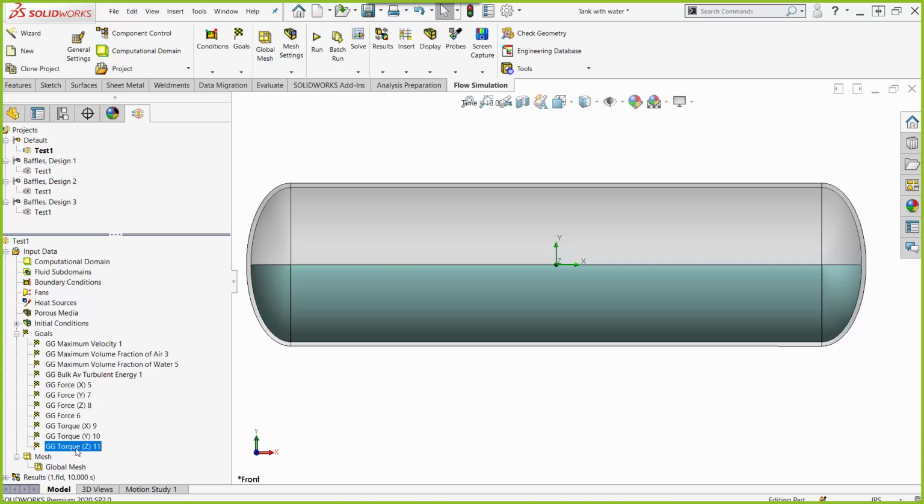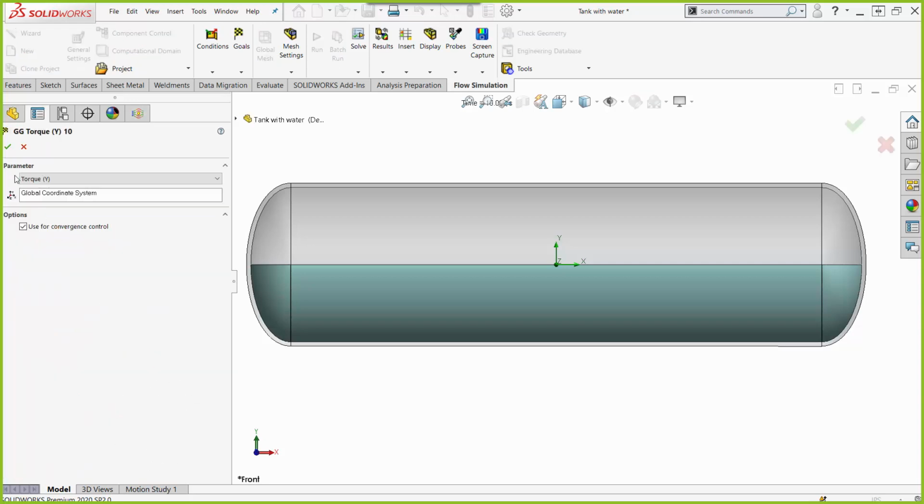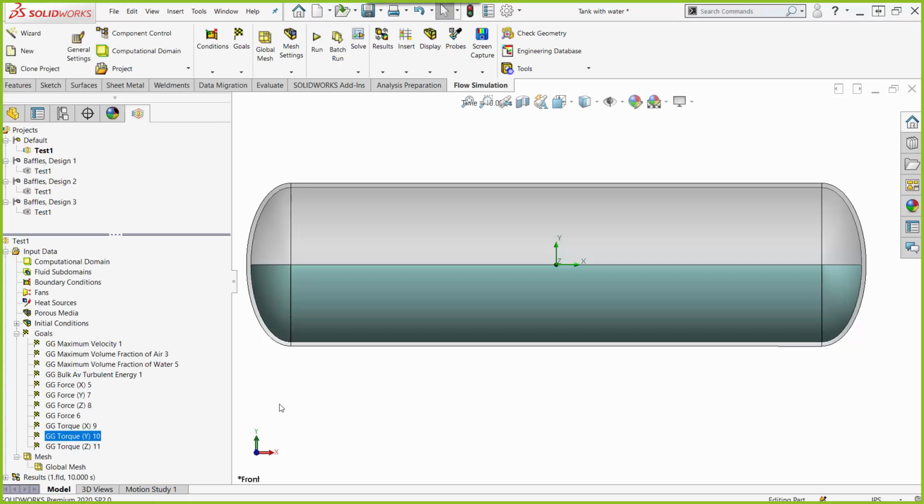I cared about pitching moment, so that's about the z-axis, so torque about the z-axis. And then I cared about just the overall turbulent energy. It was a way for me to measure how much waves still needed to dissipate, so I captured bulk average turbulent energy. You'll see I have other goals in this list, things like forces in the other directions or moments in the other directions. Absolutely an option for you to pick.